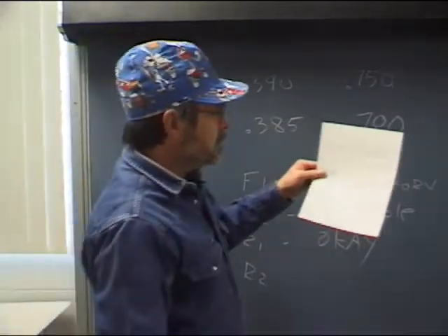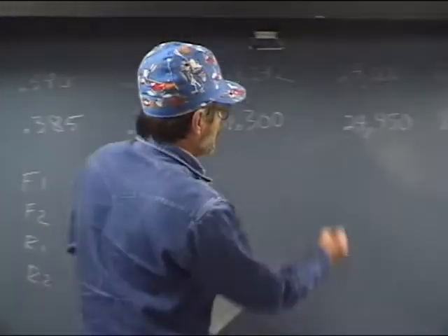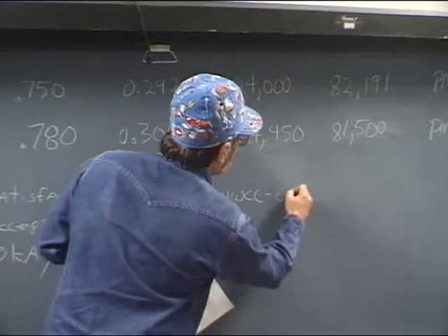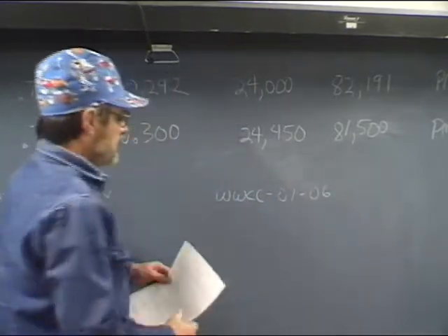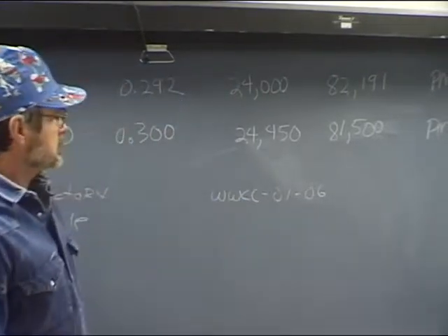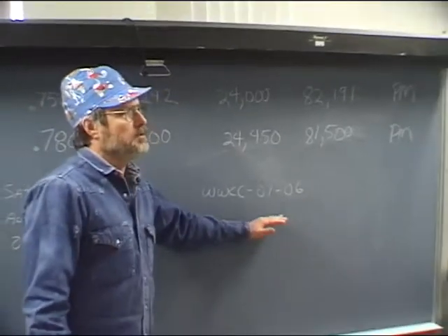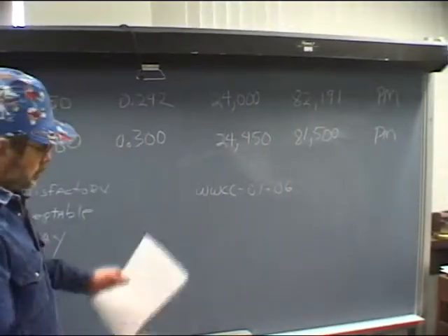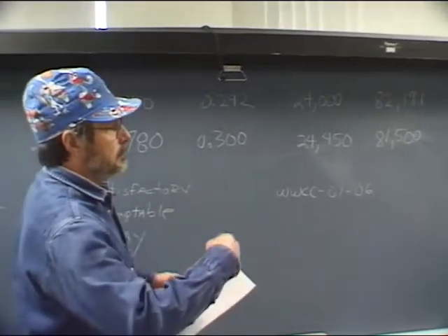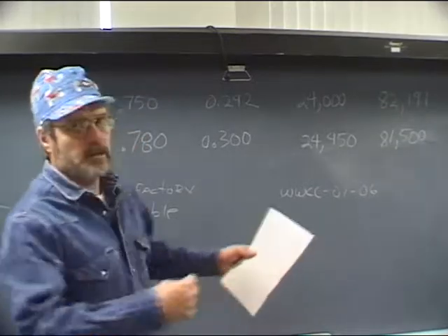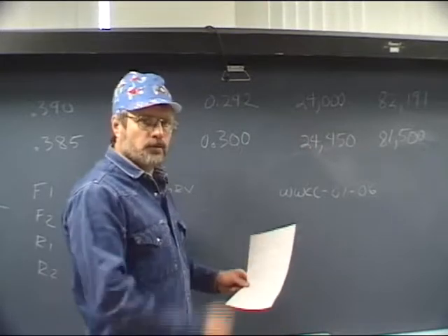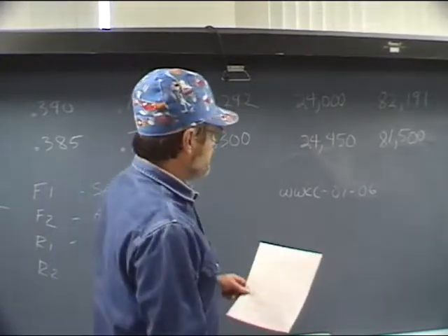And then you have to have a unique laboratory test number. So I would probably do something like WCC-01-06, meaning that it was the first test that I did in 2006. So something like that. It's got to be a unique number that you can refer back to. Then the manufacturer would be who was this done for? It was done for any welding company, and then you would sign off on it. And as a CWI, you would also affix your CWI stamp on there.